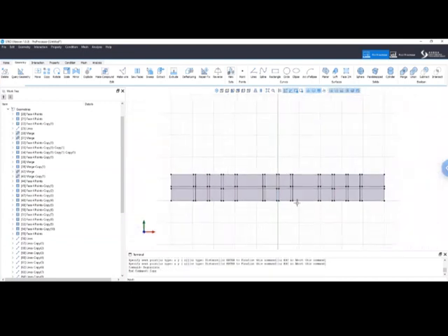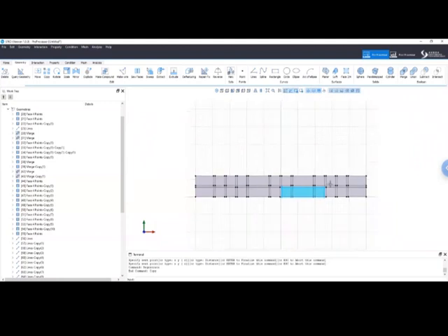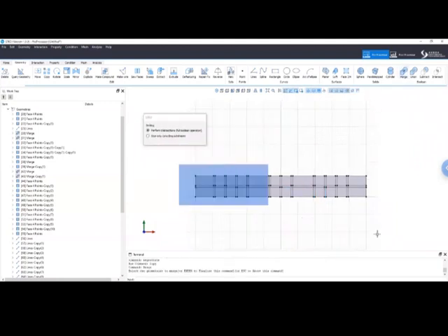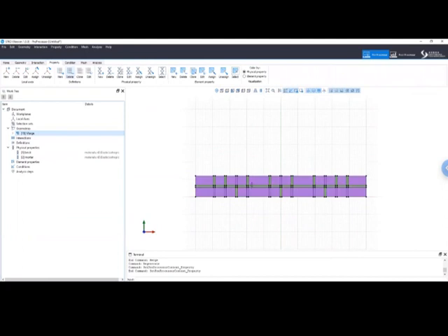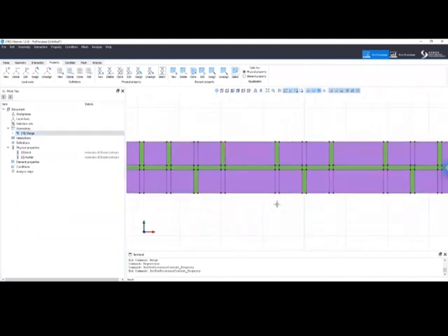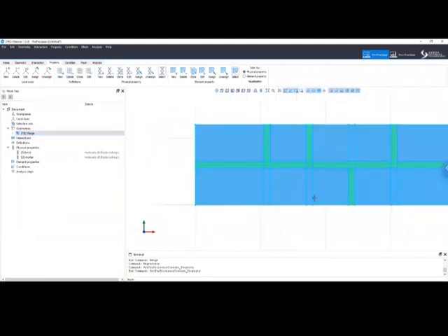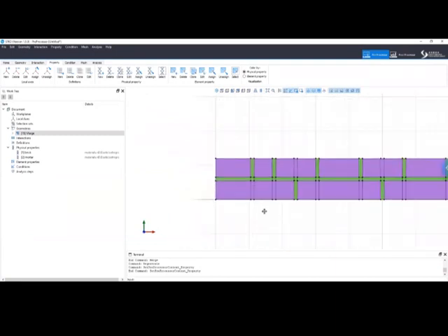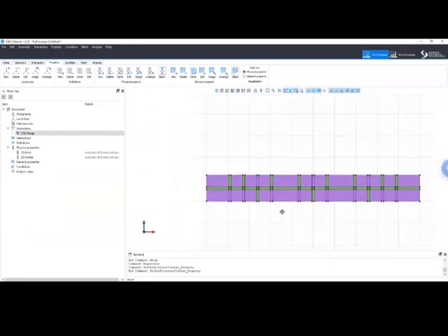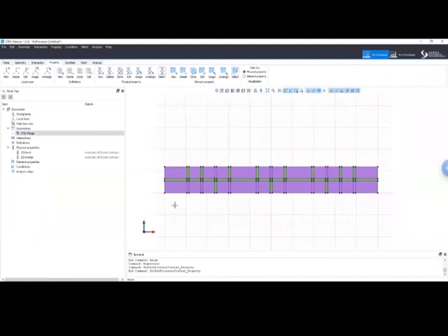Okay. Now what we can do is to create a merge command, and we attach everything. So we select everything, right click. What we obtain now is a single shell, as you can see, and the material property remains. But what's the difference? Now we have divided the brick into sections in such a way that every face has exactly 4 corners and 4 edges. So they would be suitable for quadrilateral structure mesh. So now this is fine.